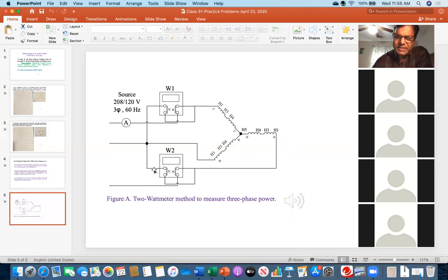To measure the voltage, you need 2 points, right? You all know you can measure the voltage across 2 points. Now, if you connect one end of your voltmeter to this coil, then where would you connect the other point? Because you don't have any neutral line here. This is a Y connection, but there is no neutral line. So if there were a neutral line, then you could connect the other end of the voltmeter to that neutral line. But because neutral is absent in this case, that's why you are connecting the other end to this common point.